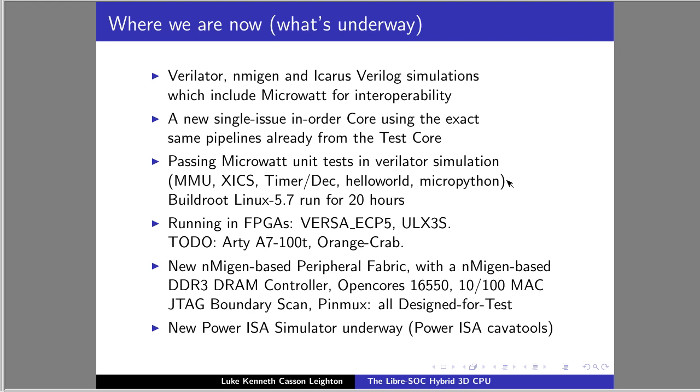At what priority wanted my attention? Was it the OpenCores? Was it the UART? Was it the I2C? No. Was it the SPI? No. And you go through and enumerate all of the different peripherals and service the interrupts. So it's this funnel, but the peripheral fabric hangs all of that together so that as an SoC designer, you don't have to reinvent the wheel every single time you just want to deliver a customer product.